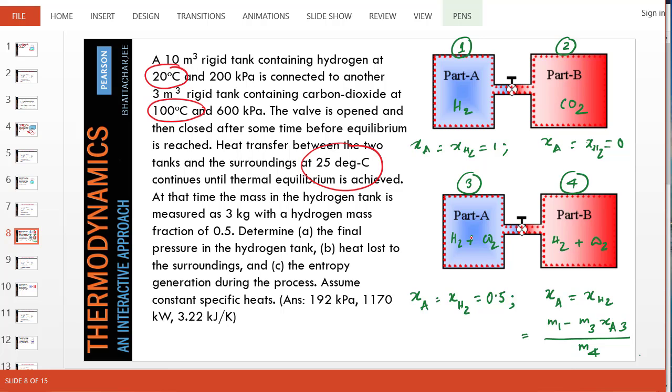So obviously, in this particular case, we're going to use a binary mixture, because the constant specific heat assumption means we are going to use the PG model. And of course, this is a semi-mixing problem, not a full mixing problem. But a few things: generally in a binary mixture, you will notice that in the TESTapp we have a variable called XA. Component A in this case is hydrogen.